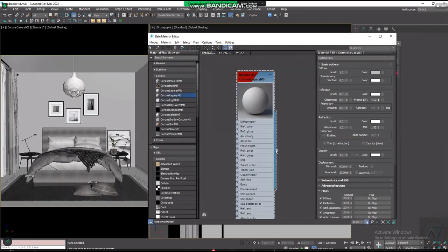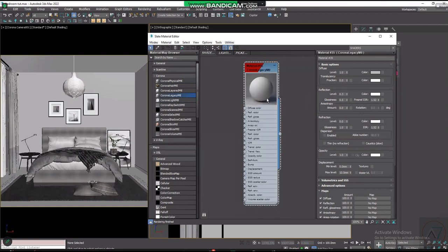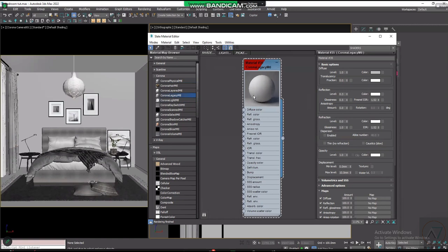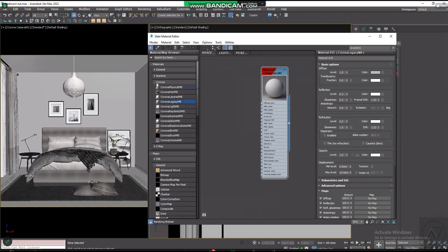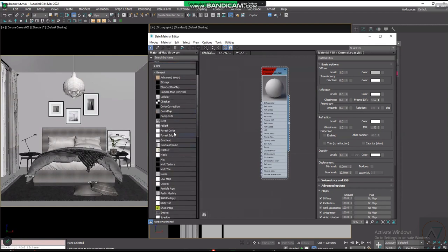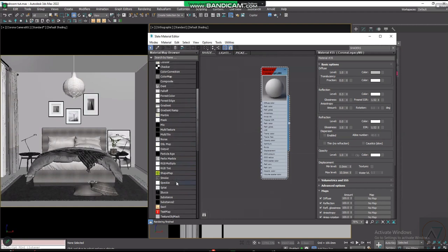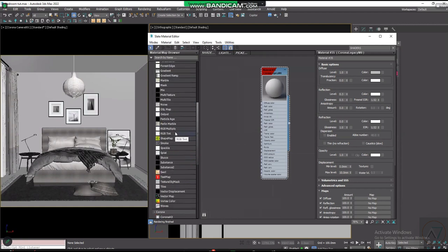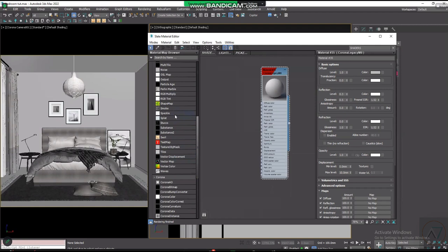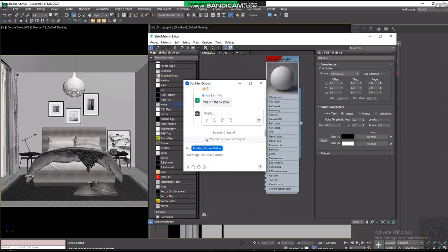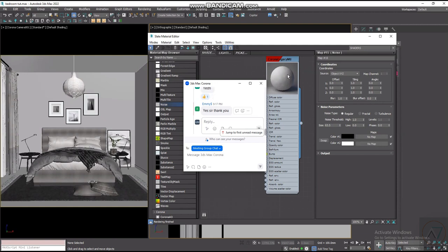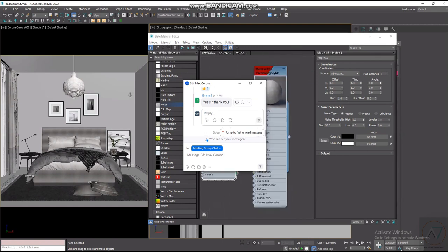So that's the thing. For this wall, I don't want it to just be flat, you know, there's nothing with it. We didn't add anything, no PBR material. So what I use to add on my own, if I'm using this plain stuff for my wall, is I come to general and add noise to my bump to give me those bumpy effects. So I use noise, just apply it to my bump. You can see now if you are looking at this guy here, it's giving me this bumpy feeling. So they are too big. Okay, let me select my wall.